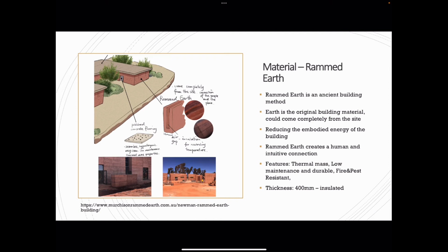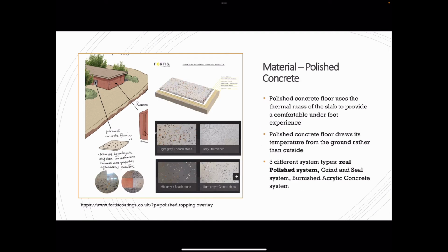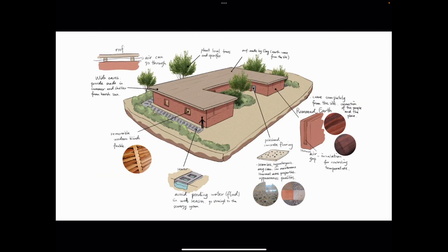The thickness of the wall in this design is 400 mm for better insulation. For the floor inside the building, as Palm Island is near the Great Sandy Desert, it's easy to get sand to make a concrete floor. The polished concrete floor is good for building a comfortable internal climate. People could even walk with bare feet on it. Now here is the drawing of the full view.